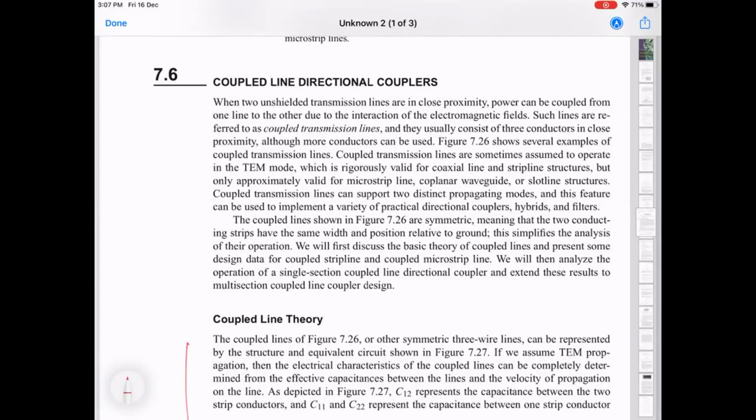One, that the rat race coupler itself has a finite physical length, so it introduces a phase delay, so one has to take that into account. And the fact that the impedance seen by the resonator is now no longer 50 ohms. It was 100 ohms because it was two 50 ohm transmission lines driving it differentially, which effectively gave you 50 or 100 ohms in terms of what the line width of the resonator is going to be.